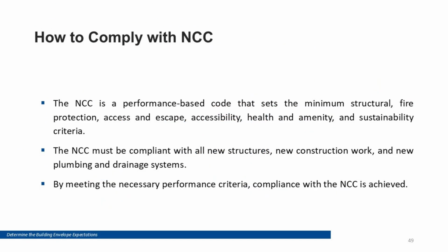How to comply with NCC. Compliance can be via deemed to satisfy, performance solutions, or a mix. Construction teams support compliance by using specified products and installation methods, keeping insulation and air sealing continuous, checking key details before linings close up. Small defects can create large performance gaps.